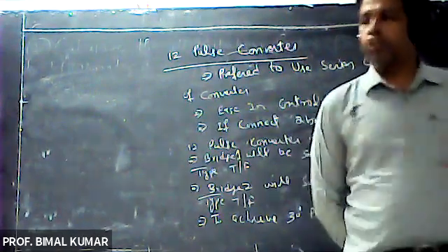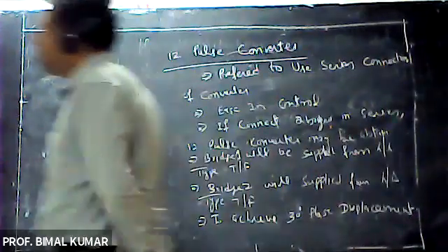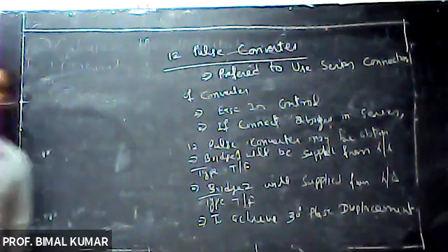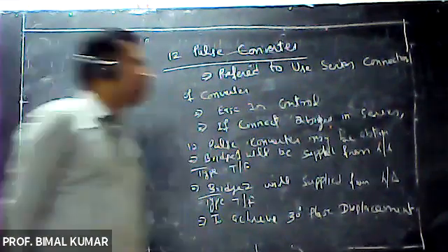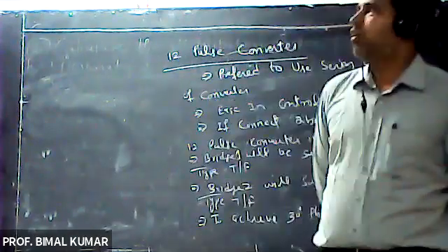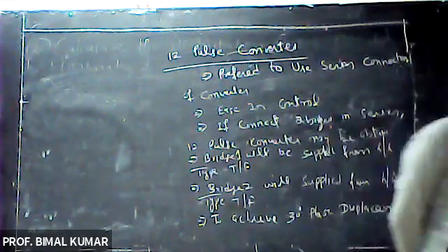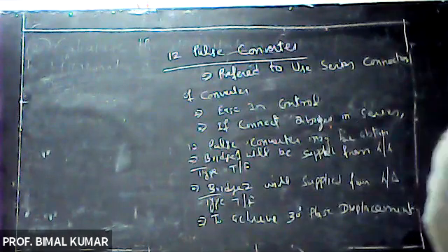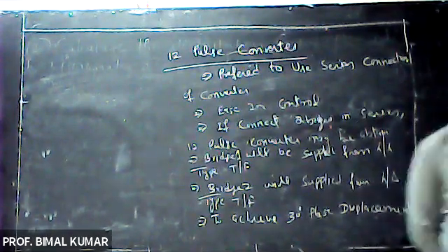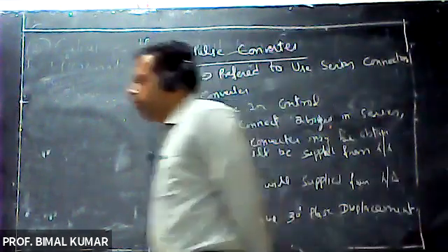We may use 6 pulse converter in some applications, and we may utilize 12 pulse converter in some applications, but the number of pulses beyond 12 is not practically possible because the non-characteristic harmonics are not eliminated, right?